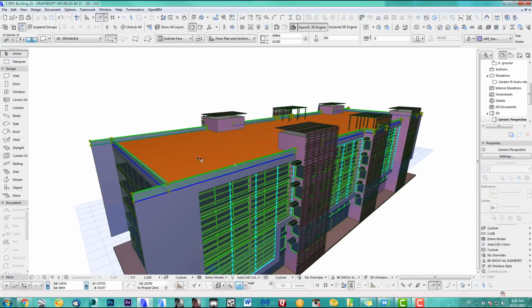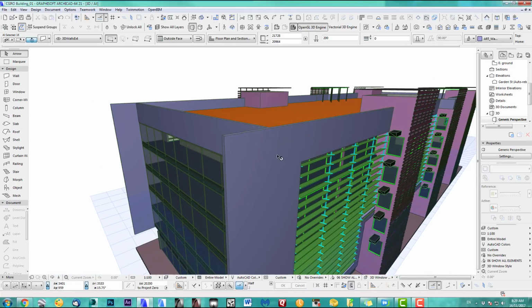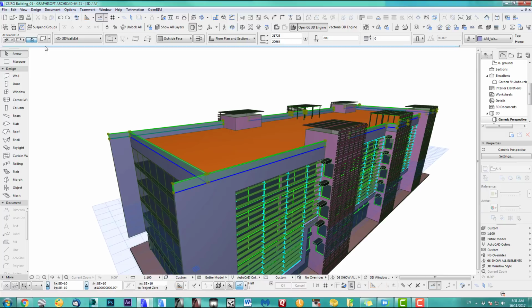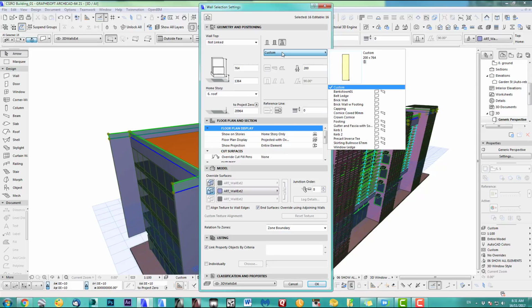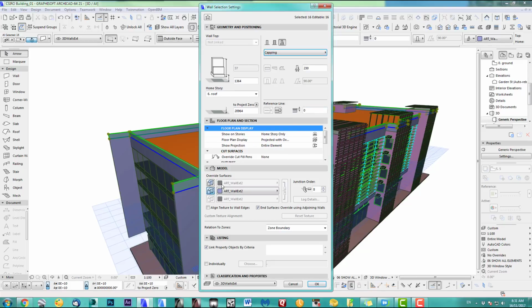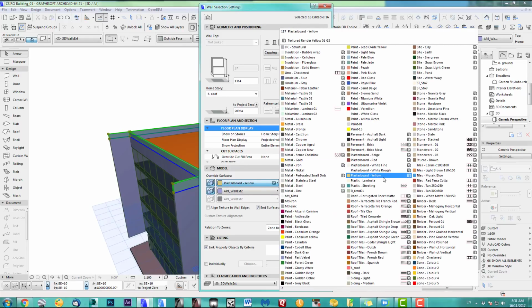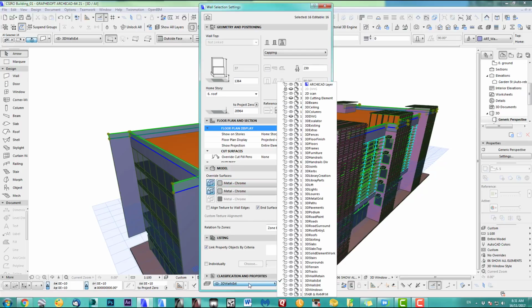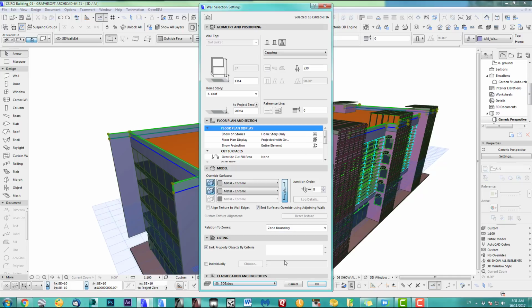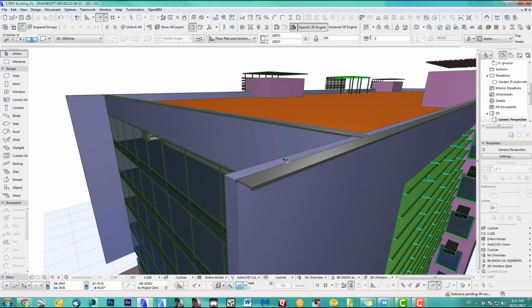So what you do is, quickly, I've got it all grouped. I drag a copy. There you go. All you have to do now is go into the wall settings and change to our profile up here, and we take the capping I showed you before. Make sure you've got the right material, which I've got on chrome, metal chrome. And if you want to move it to a different layer, just do that. I put it on an extra layer here. Click OK.